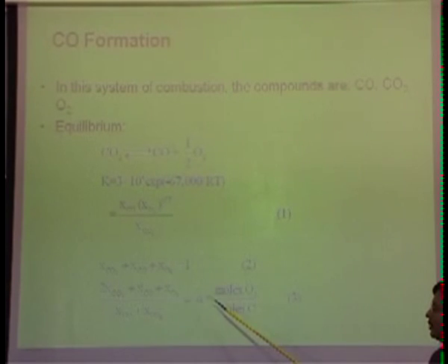If I change my alpha, if I am putting more oxygen, things might be different, or if I am putting more carbon. But what is in my hand to operate, C or O? Oxygen, generally, by and large. You are putting the same amount of fuel, that is fixed. Combustion engineers will vary the air amount. So generally when we think about alpha, we are really changing the oxygen.